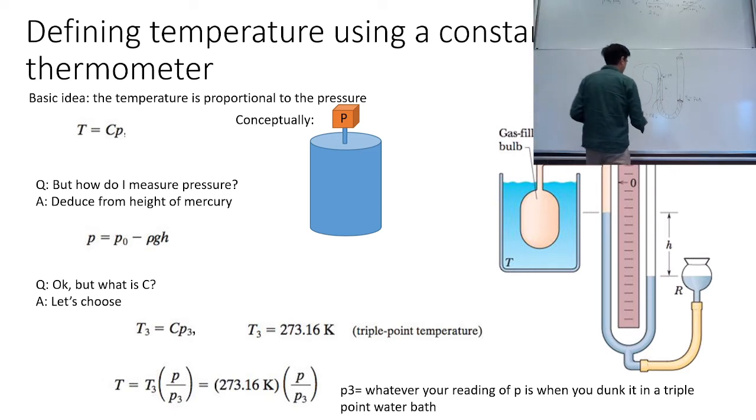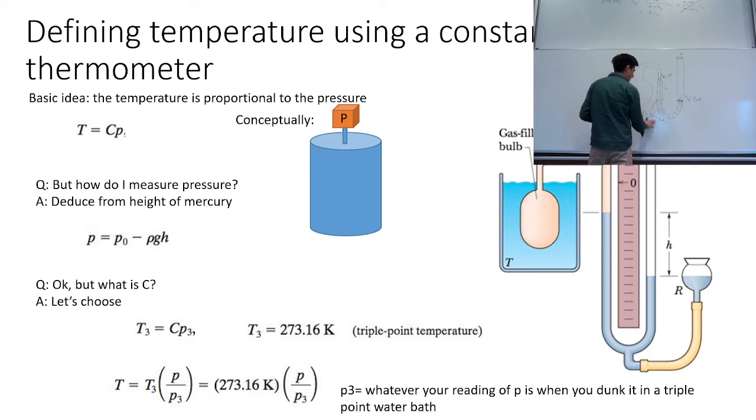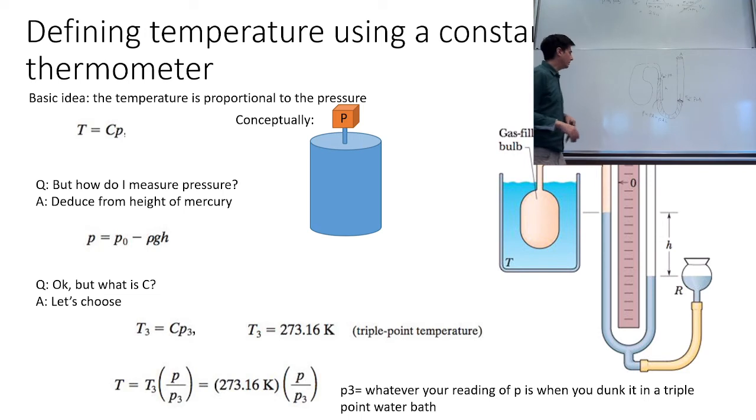And the weight of the mercury is the density of the mercury times the volume of this column here, and the volume of the column is AH. And these two things basically all have to be equal to each other because these forces on either side balance.